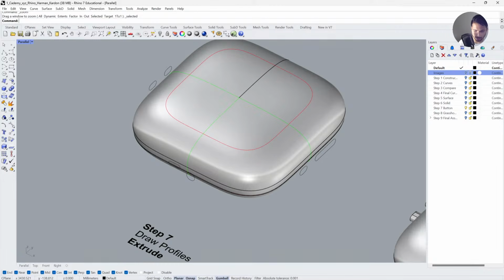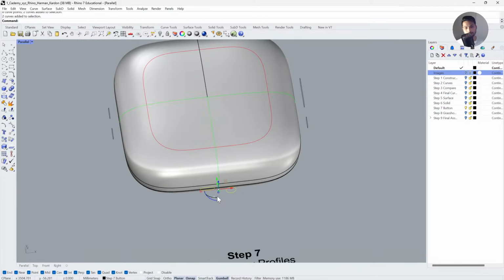You're asking if 0.35 is a standard measurement? And standard wall thickness? Yeah, 1.6 could be a standard wall thickness depending upon the material that you are trying to manufacture the part from, and depending on whether you have internal structure or perforation in this case. It will totally vary, but that is a general number. So 1 or 2 millimeters, 1.5, 1.65.